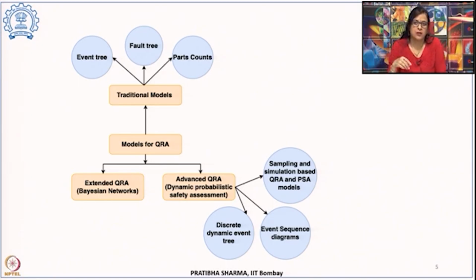So it could be some nearby fire, or an over pressurization, or a certain leak which has developed because of embrittlement. So, identifying the initiating event, thereafter looking at what has been the influencing parameters which has led to the catastrophic incident, then how these influencing parameters have interacted with the initiating event resulting in the consequences.